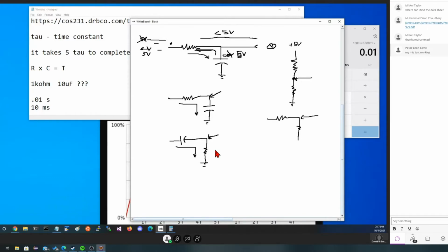And that makes a difference. This particular configuration, where I have the resistor before the capacitor and I'm looking between them, is something that we call a low-pass filter. This configuration down here, bet you can guess what it is: a high-pass filter.